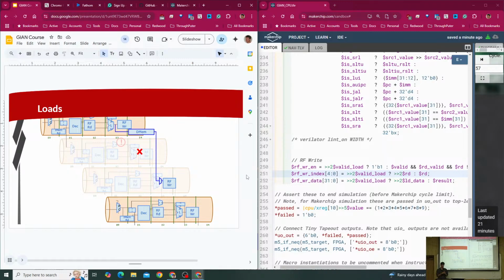It could be that during reset, we're getting random values of our instruction signal. That might get interpreted during reset as a load. So that would be a load, but not a valid one. We wouldn't want that instruction to have an impact on the register file, right? We only want valid load instructions to have any impact.